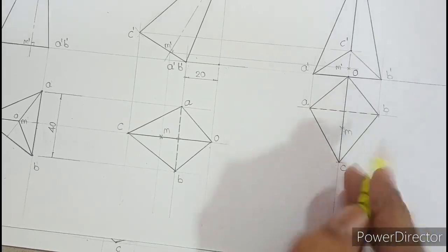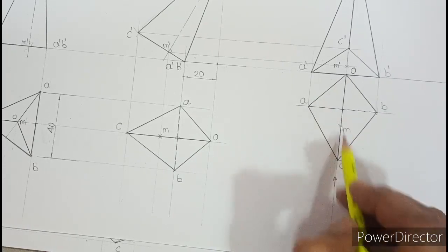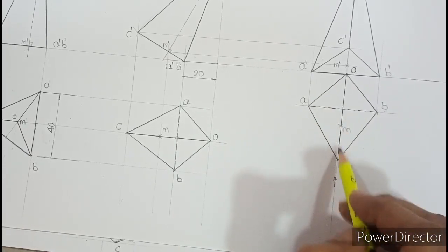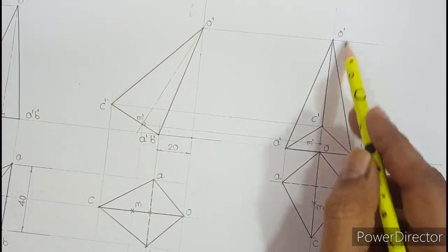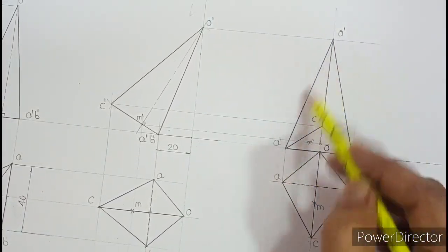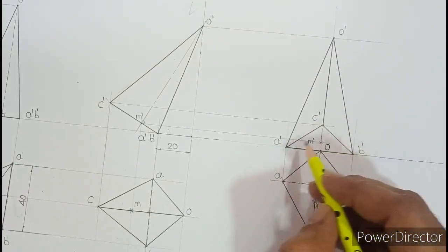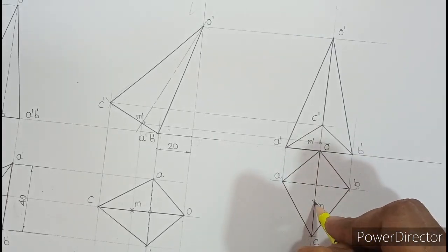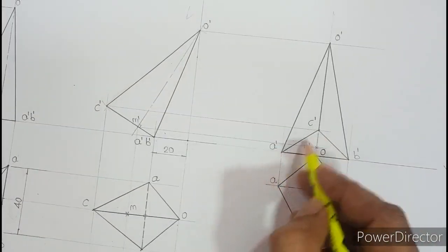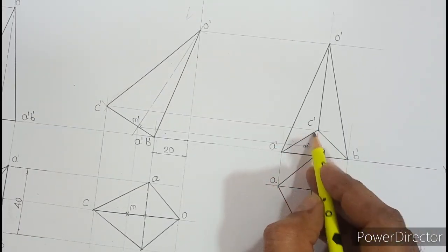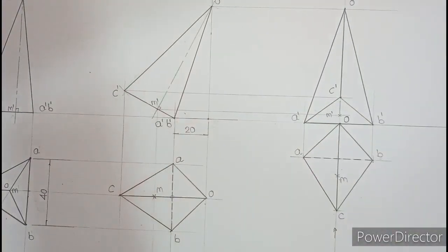Now looking from this side, if you compare apex O with M, M is near means base is near. So therefore base will be seen. So after projecting all the points, join the outermost points by dark line first. Okay, second step, if you look at the base ABC, it will be seen because M is near. Moreover, if you switch on the bulb, you can see C to B and C to A, so therefore they are dark. And finally from dark corner, draw dark slant edge CO. So that is the third stage of the given question.